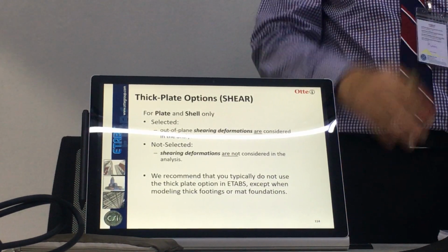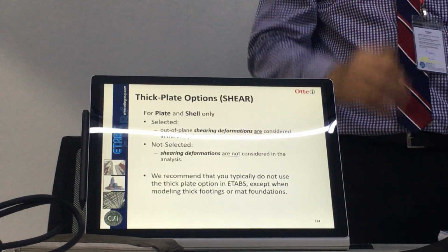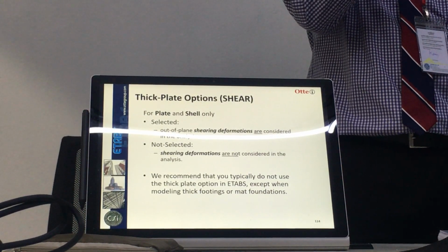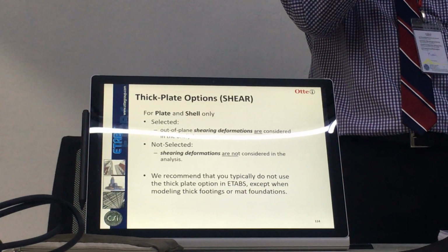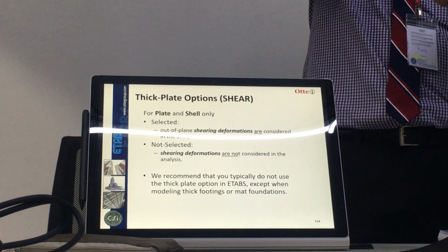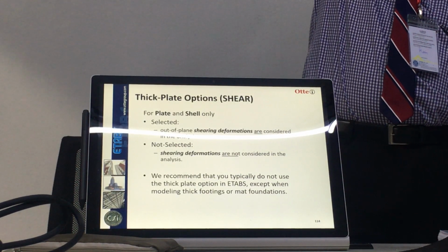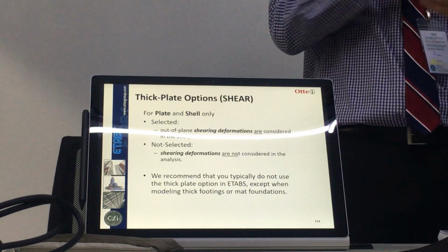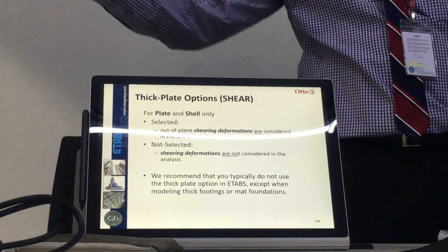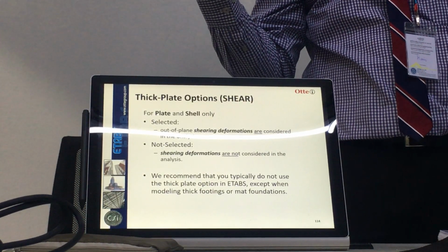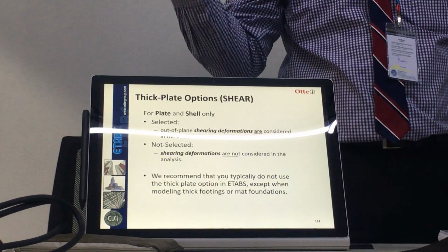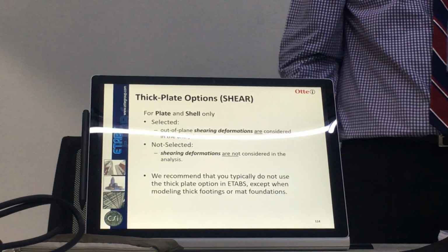For this 300 by 600 beam, the shear gives you 0, all due to bending, flexure deformation, right? But when you increase the depth from 600 to 2 meters, still 300 wide, and do the same calculation again, now you see the shear part coming up with a lot of value. That is deformation due to shear. Yeah, so that is what you mean by shear deformation.